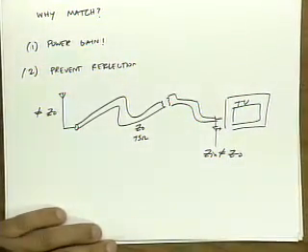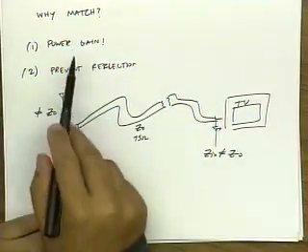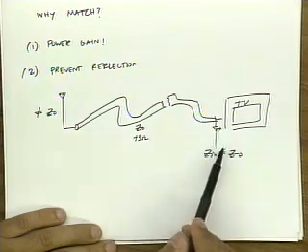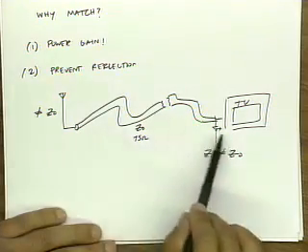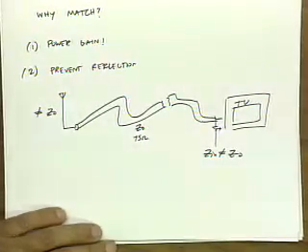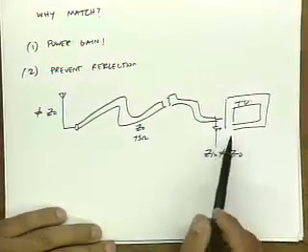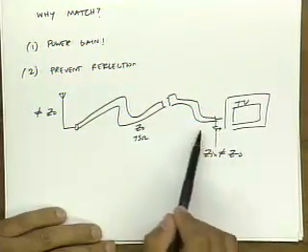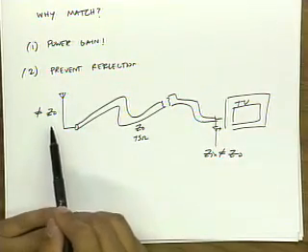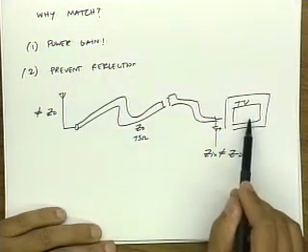What's the big deal? Well, first of all, you're not going to transfer the maximum power. That we've already talked about. But the other problem is that you're going to get reflections. The reason you don't get maximum power is that power is reflected from this television. And this is something we study in 117 when we study transmission lines. This reflected power is going to come back to the antenna, and if the antenna is also mismatched, it's going to reflect again.